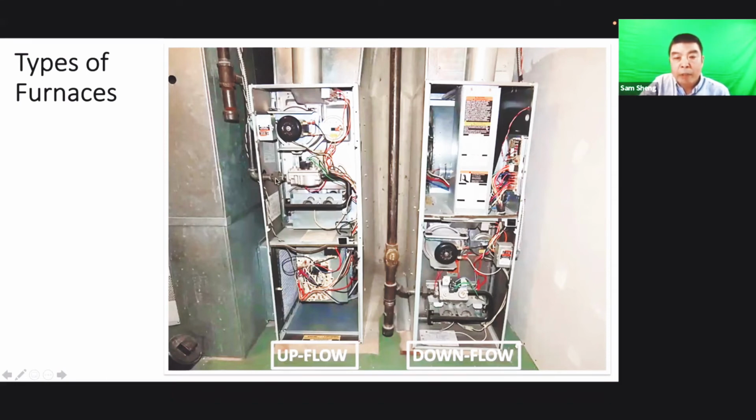It goes through a small part, and there's a handle here. It can just shut off the gas by the handle, not by the gas valve. So this is a very old furnace. If you meet that one, it's better to make a note that it's very old and recommend changing to a new furnace.